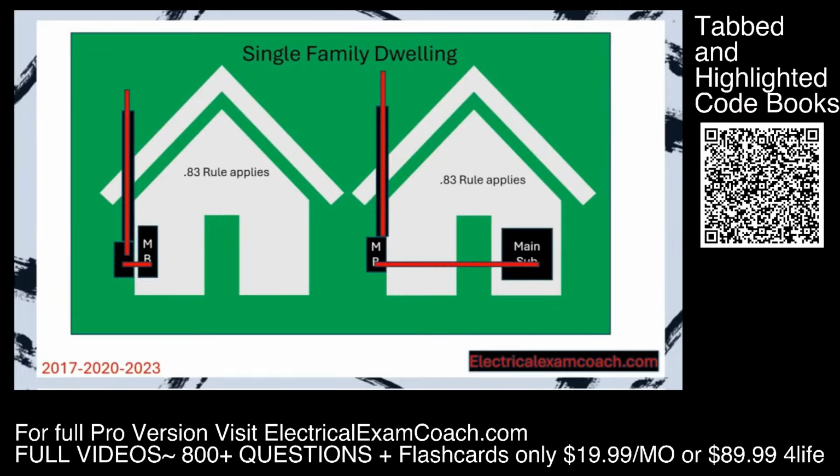You're not allowed to use it on other sub panels or on any sub panel that does not feed the entire structure. You have to be very careful with that one. So we're allowed to apply it on this one on the left for the whole wire. We go use that table and size our wire based off the table. And the scenario on the right for all of that wire there for the service itself, and then also for the main feeder, as long as that panel that it's feeding is feeding the entire structure.